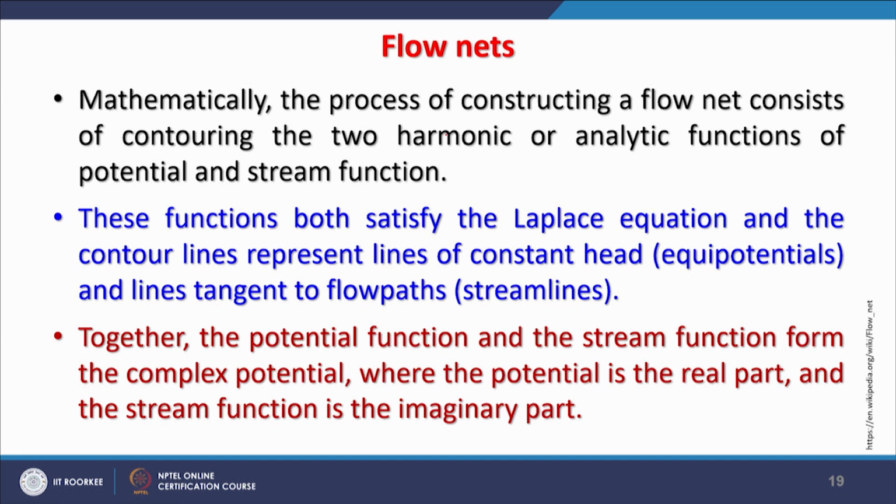So, with this I end this discussion about flow nets and flow lines or groundwater flow, where we can identify using flow nets where the recharge areas are, where the discharge areas are, whether the river is effluent or influent, and so on. So, with this I end this discussion.